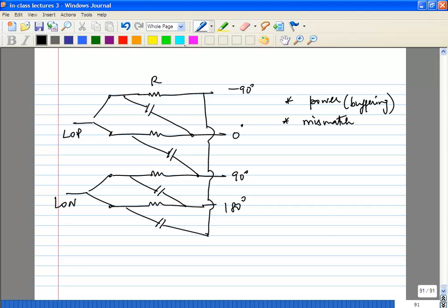As you go to higher and higher frequencies, this becomes a problem, because both R and C become small, first of all. And now you want to make your R as large as possible, so your capacitance becomes really small. What is the other way of quadrature generation?